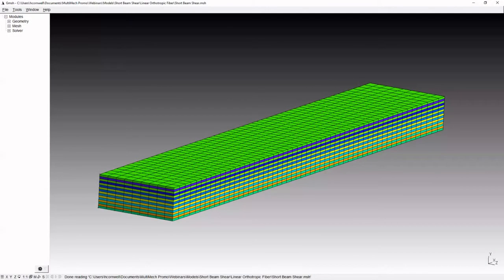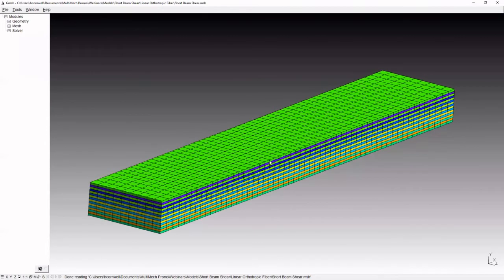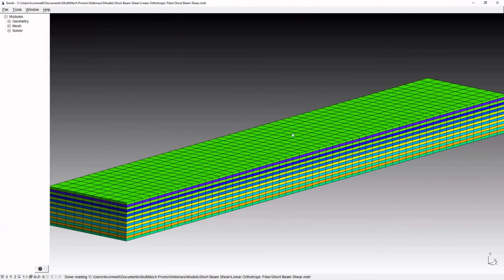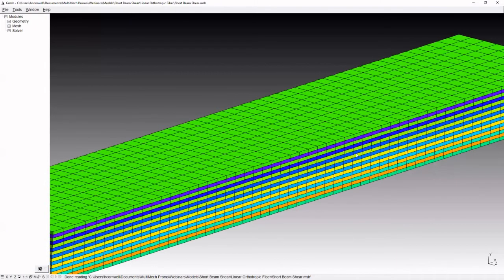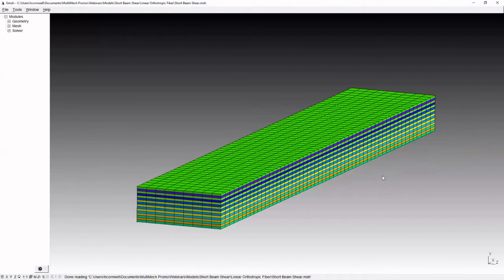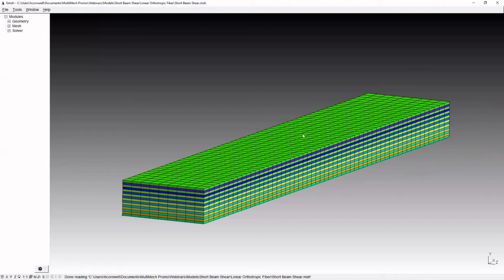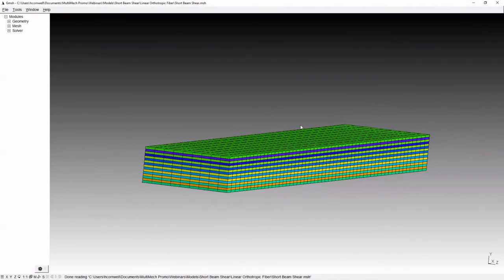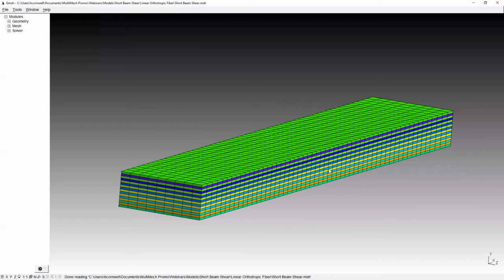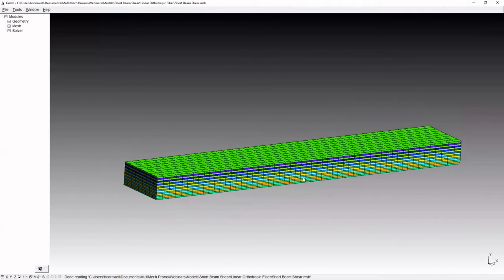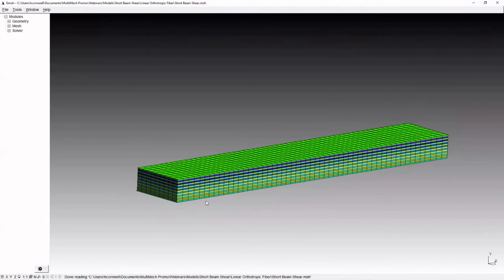Now we'll apply this to an actual part and run a multi-scale analysis to show the differences in the results you can get by incorporating the bi-modulus material model. So this is a global part that we're looking at. Very simple. It's a layup that has, I think, 16 plies. What we're going to do is apply an RVE that was shown before, and orient it in the X direction shown here. So the stiffness is going to be really high in the X direction. And we're going to run a 4-point bend test. We're going to fix some node sets on the bottom and the top.